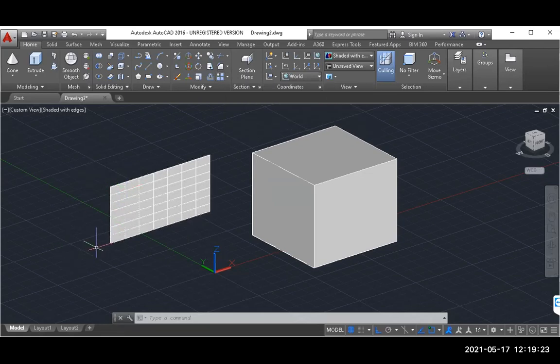Yes. The line was here, and I had made it expand or stretched it in vertical direction. This surface also in this direction. Okay. Now, if I have to extend the surface that is not in perpendicular direction, in that situation, what I will do? Okay, here the path of extrusion is in normal direction or perpendicular direction. If the path is not normal, if the path is not a straight line, in that situation, what we will do? Let us see. Let me come out of this annotation. Okay, I will use the span.